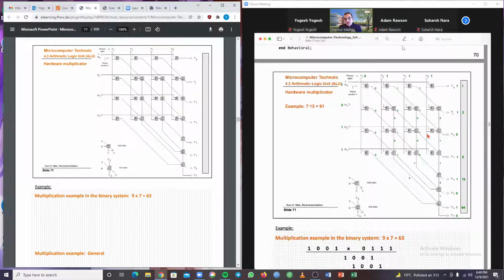We also are not needing subtraction at all, because subtraction means adding the 2's complement. So the basic operation of all arithmetic operations is addition. If we are able to execute an addition, and to represent numbers in 2's complement, we can construct all other operations based on this fundamental operation.